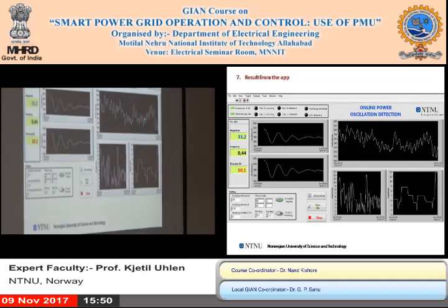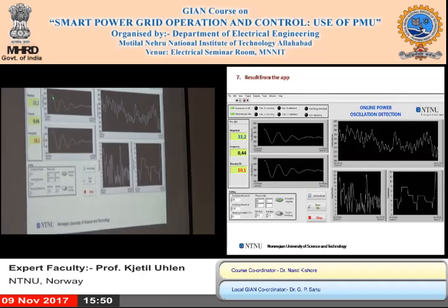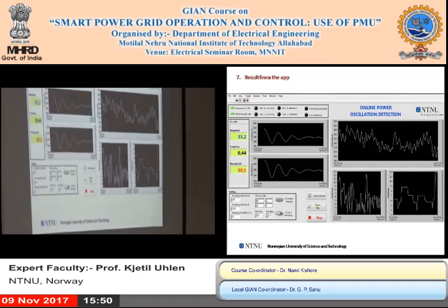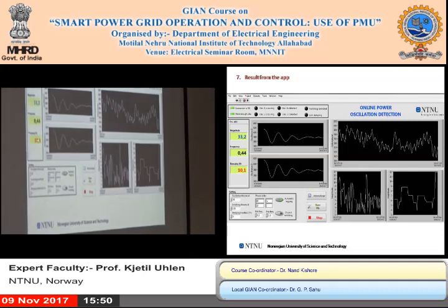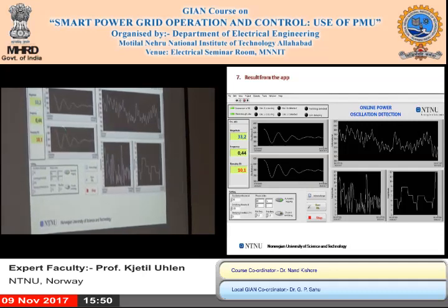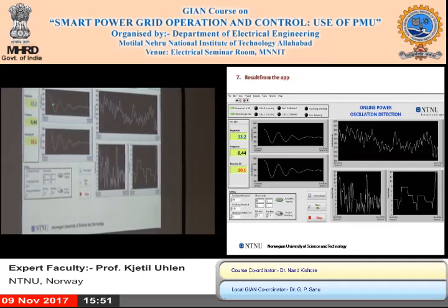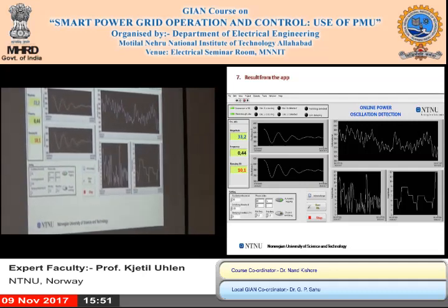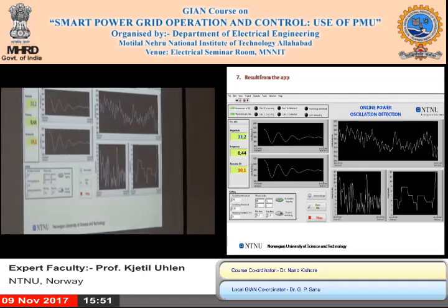But sometimes there is a disturbance that creates a ring down, and that is captured over here. And in this case, this captures something at 0.44 hertz and damping of 10%. So this pops up now and then when something happens, and should be able to give the operator sort of a confidence of the damping of the system.